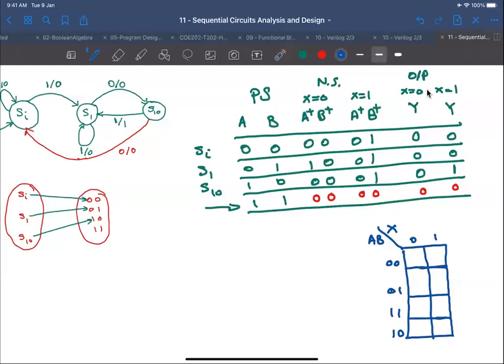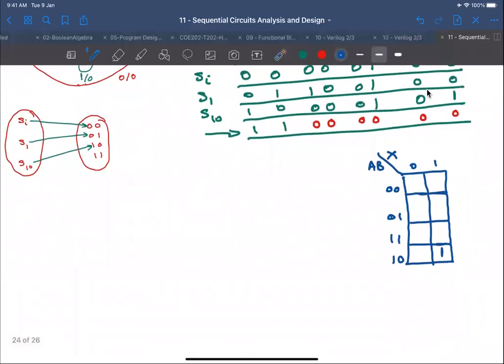I think, yes. And no, column number 2, the last row. Excellent. Just make sure that you don't do it this way. Okay, it's not this. This is wrong. It's this one, because we have 1 1 0 1, and this is 1 0 1. You see that? So this is nothing but a minterm. So my y is going to be minterm number 5, which is A B complement X.